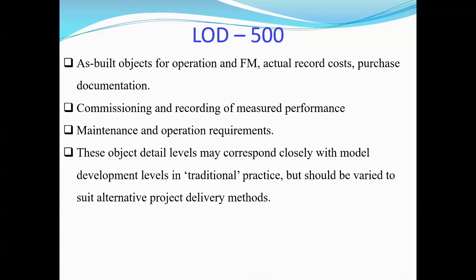The 500 series is the as-built model, mainly for the facility managers. They keep the records. Normally, the purpose of the as-built model is mainly twofold. The first is to maintain the M&E, the mechanical and electrical services. So let's say in one area the electric power goes out, then they can go back and see the design, see which area it is located in, and then go and repair it. That's the main actual purpose of this model for the facility manager.